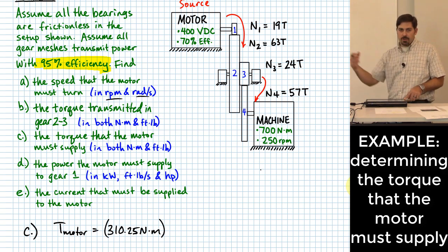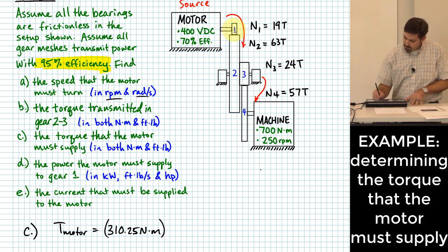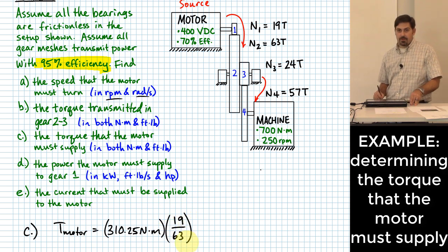Bigger gear, more torque, smaller gear, faster, right? Smaller gear, less torque, bigger gear, slower, right? So we need to multiply this to find the torque in the motor by whatever direction the ratio needs to be to make that number smaller. Okay? Does that do it for us?